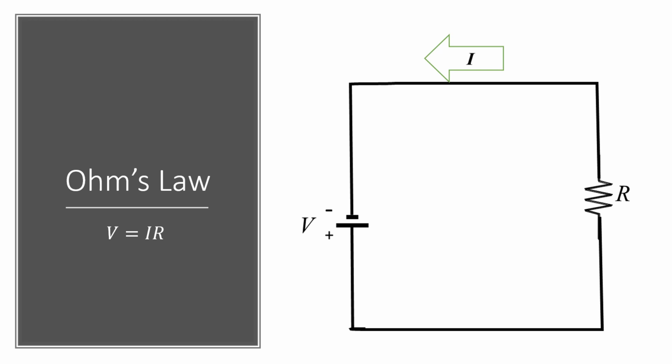In many cases, we might know the voltage and resistance, basically from the components that we're dealing with. So we have the V of some particular battery. We buy a resistor with a particular number of ohms, and we can calculate the current that we'd expect to see in a circuit like this by simply dividing V by R, and we'll end up with I, the current.